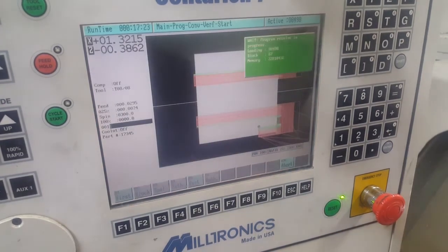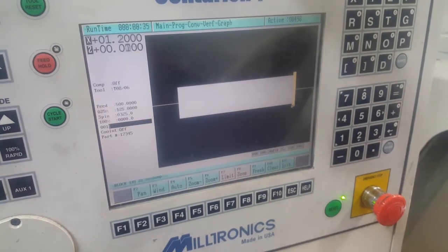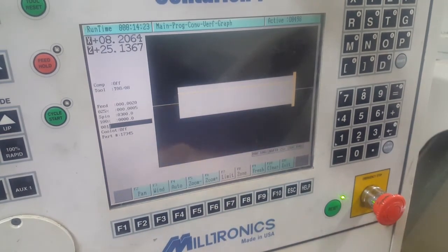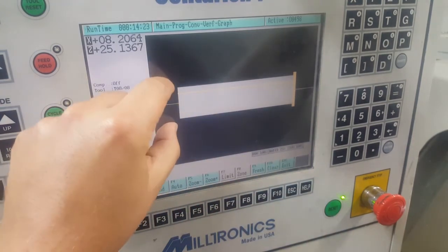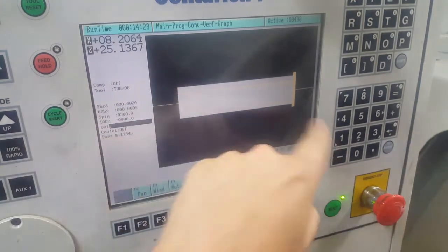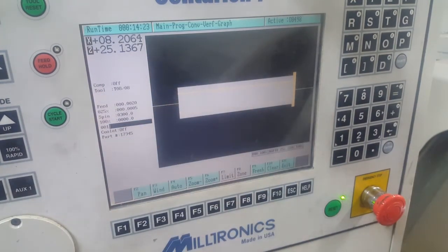And verify. So going to face it, drilling, and then a little boring operation. And then I'm going to have my part a little bit long. I should have thought about that before, but I'll leave an extra ½ inch back here, and then hold on to that, put a center in, turn my outside. So I'll do an outside turning for that second operation now.